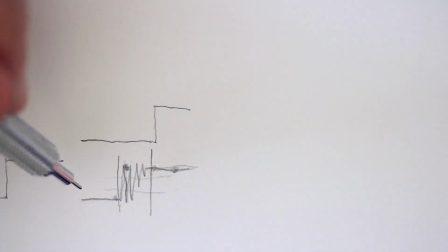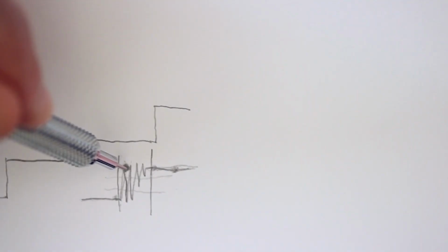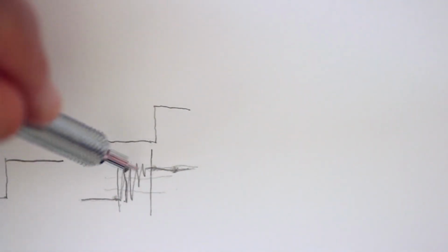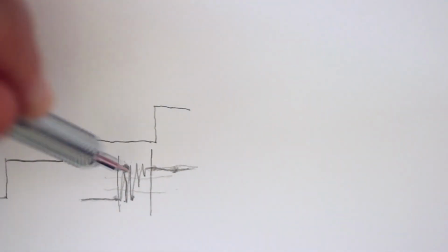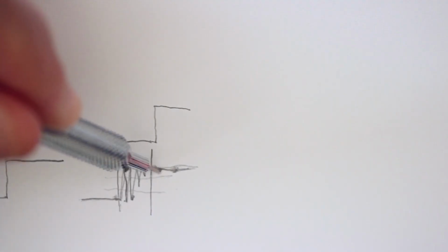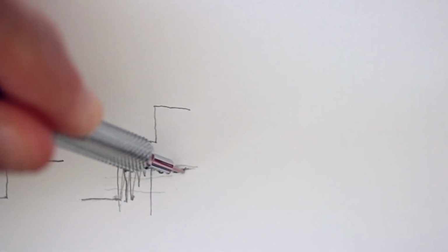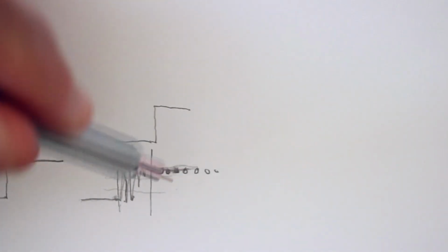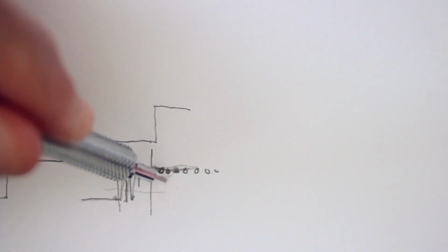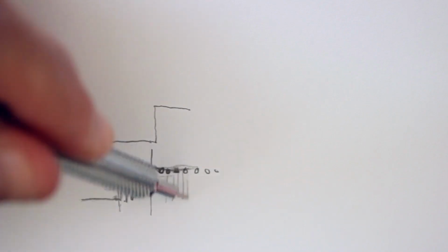Alternatively, I would like to have the program on every cycle test whether this is a 1 or a 0. If it's a 1, every cycle it'll test it again to see if it's another 1. If it's a 0, then it eliminates it. It's not pressed. But when it keeps doing that and gets to this point, it has to keep doing the cycles until I get maybe 500 or so of these. So I'm able to do other programming within these cycles. I can do all kinds of other code inside of these cycles.